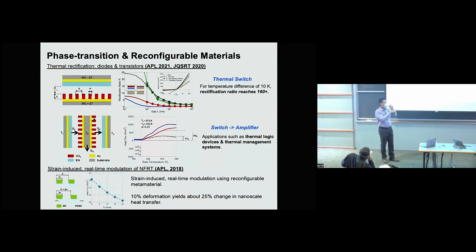diode and the thermal transistors made of phase change material, VO2. Vanadium dioxide has a phase change temperature around 341 Kelvin. At temperatures higher than this, it turns to metallic form. Temperature less than that is the dielectric, insulation form. So we simply use this material to design a non-contact mode, radiation-based thermal diode to control the radiated heat flux from one direction to the other.